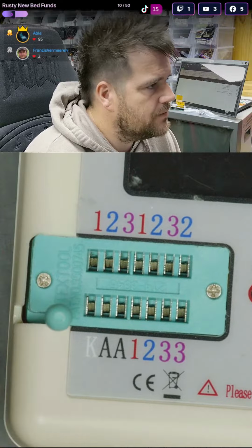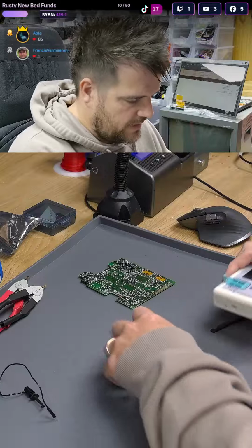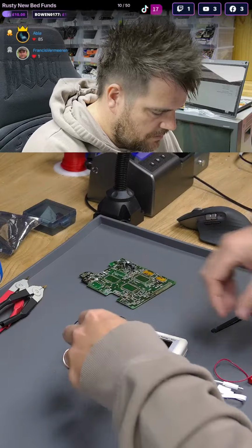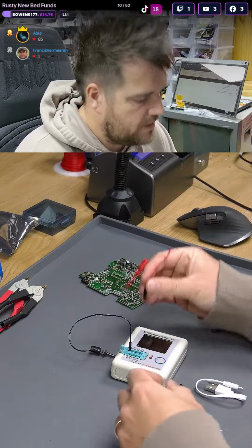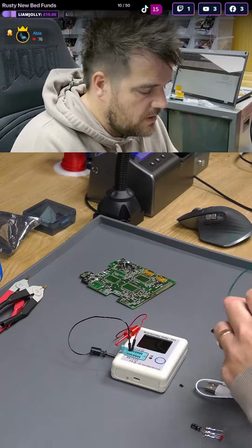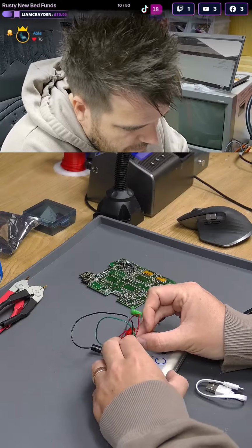A and K is anode and cathode for testing diodes. So basically we're just going to put the 3 leads in, 1, 2 and 3, and then remember the order, because when it figures out what components are, it shows up on screen and says, you know, pin 1 is this, pin 2 is this, pin 3 is this. So that's the only relevance. You can put them in any order, but it'll tell you on screen what the pins are.